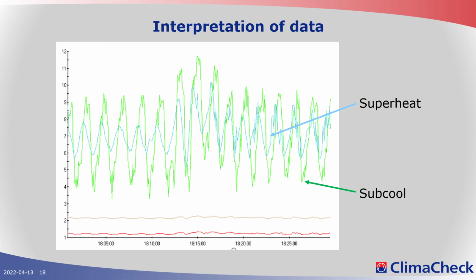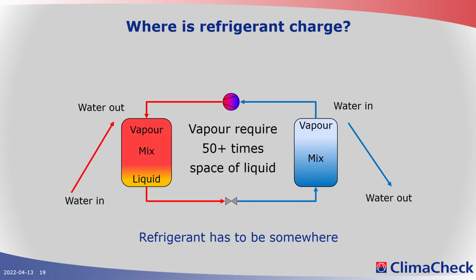So these interact, which is important to understand, because if you get flash gas as the subcool is not sufficient at the dips, it's going to interfere with your expansion device. So you need to, even at the minimum subcool, have sufficient liquid to give the expansion valve a reasonable chance to operate well.